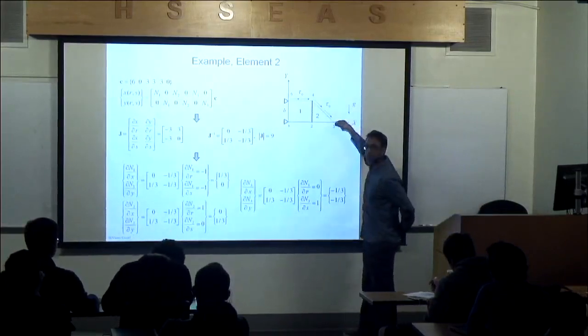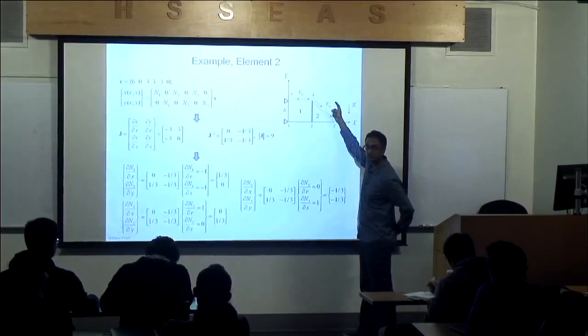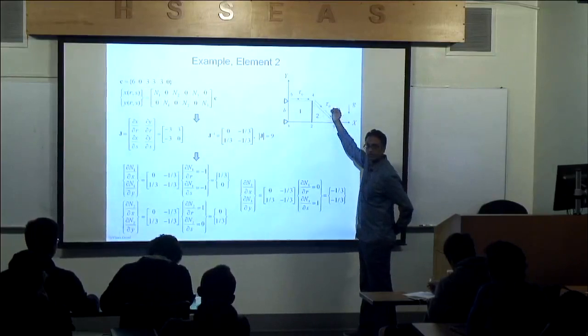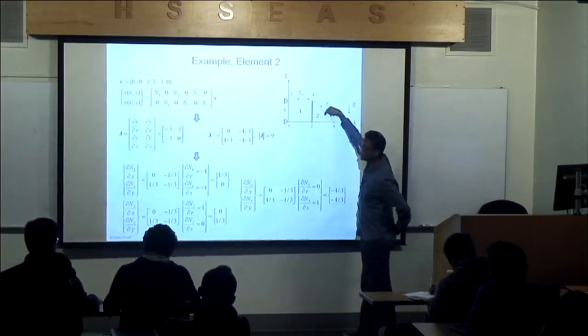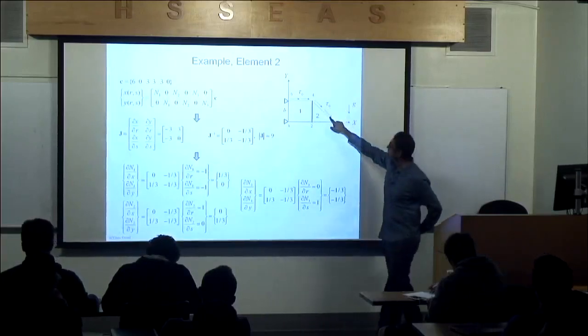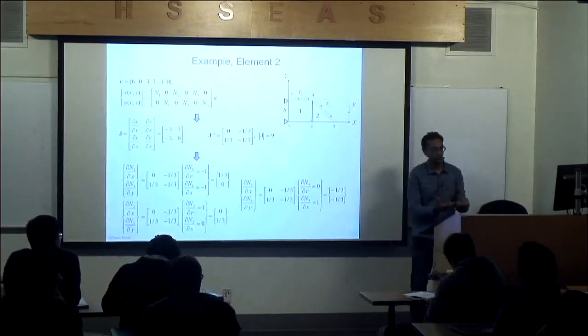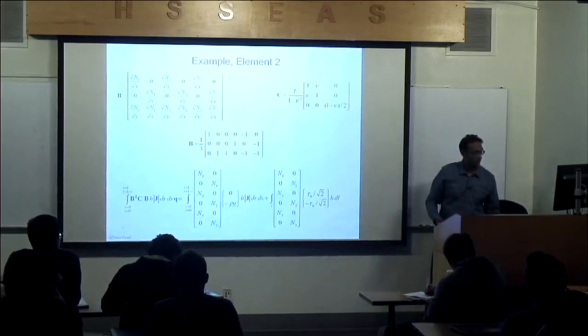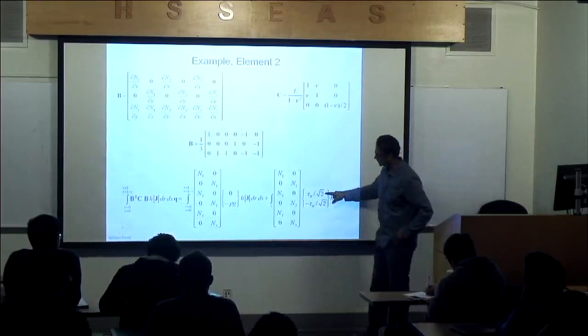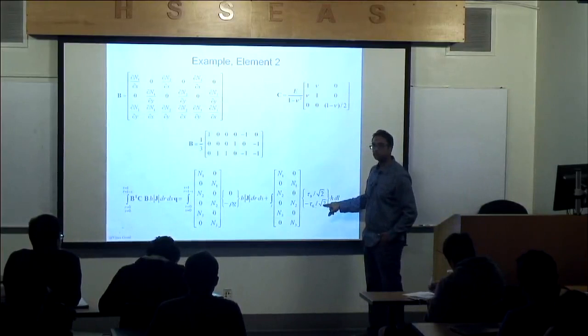Okay, you agree that the traction acting in the x direction is basically tau 0 square root of 2 over 2 to the right, and then the traction acting downwards in the y direction is tau 0 square root 2 over 2. This is a 45-degree angle. This is 3 and this is 3. Of course, I chose numbers that are quick for me to implement. So that's why you see a tau 0 square root of 2 positive and minus tau 0 square root of 2 over 2 because it's going downwards. Okay.